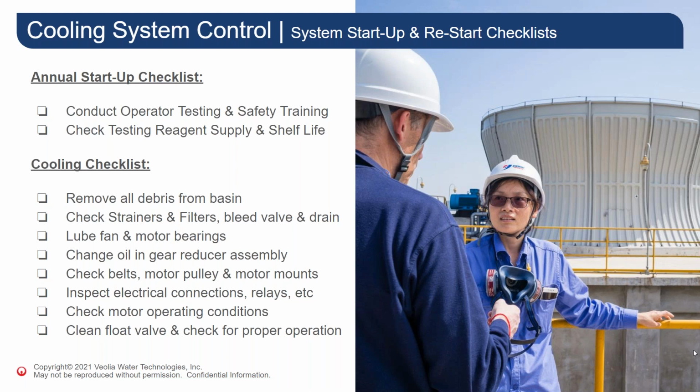Corrosion is the return of the metals to their natural state, much like steel rusting in a yard in the rain. Corrosion requires the presence of oxygen, water, and a metal, which are all present in the cooling system. Fouling is the accumulation of unwanted material on solid surfaces. The fouling materials can consist of either living organisms or non-living substances.